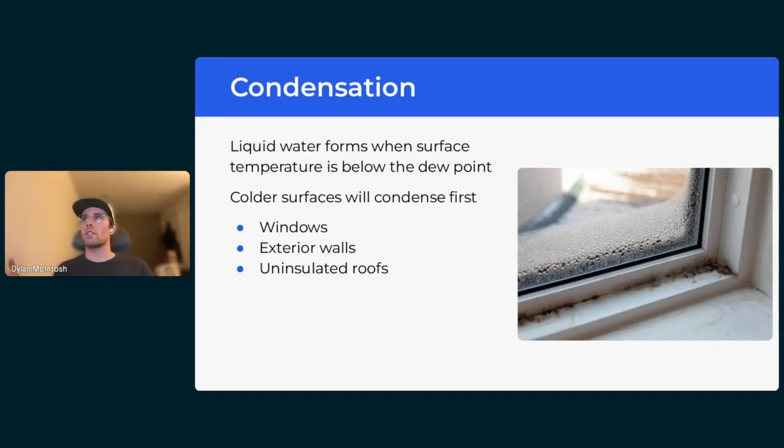Under-insulated walls, maybe the insulation has settled in a weird way, causing air gaps. And I've seen it where picture frames that are on exterior walls can trap moisture better than just the open air where the air is moving. And I've seen condensation occur between the photo and the wall, where you take the photo off the wall and there's nearly a perfect square of mold growth from that moist air getting trapped on that exterior surface.